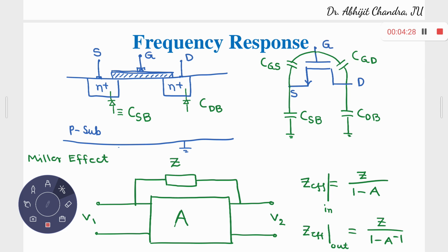So you have two conductors, and in between these two conductors some silicon dioxide, the insulator, and this gives the notion of a capacitance. Discussing the device physics of this MOS transistor, we started our discussion from that perspective only. It is a capacitor. And what is the value of this capacitor? We have assumed C-ox, the oxide capacitance per unit area.